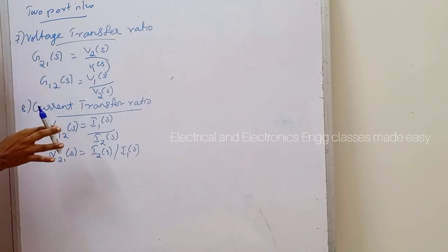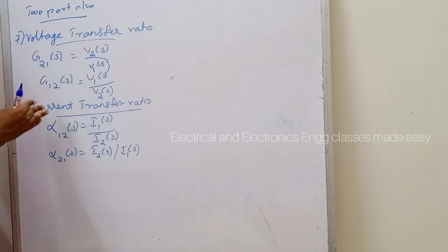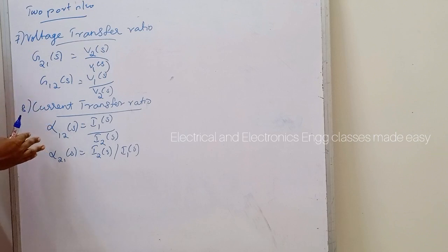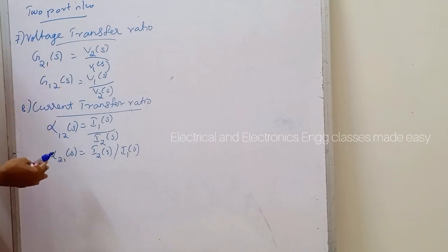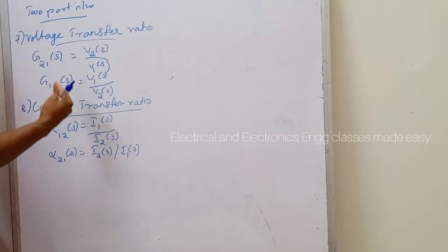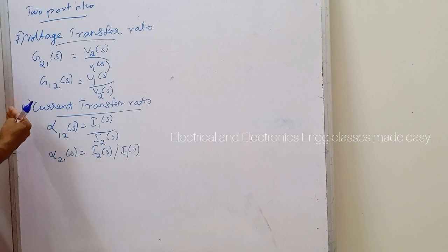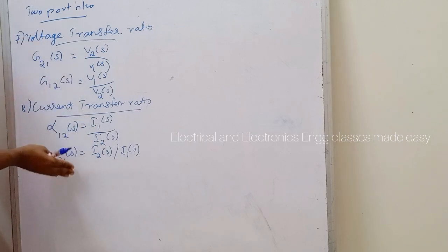So, these are the network functions. These network functions are found by forming the system of equations using node or mesh analysis, and taking the transforms of the equations by setting the initial conditions to 0 and solving for the ratio of the response to the excitation.